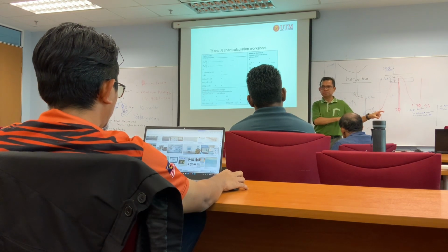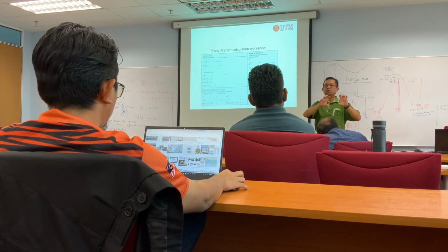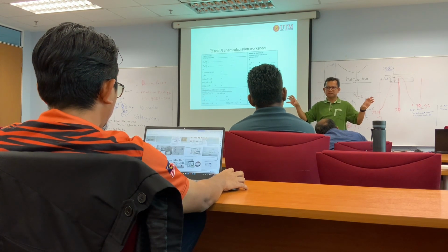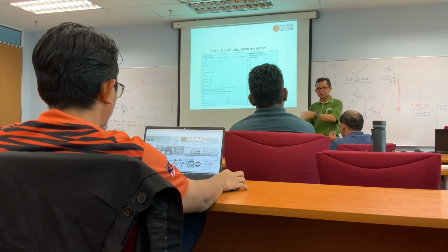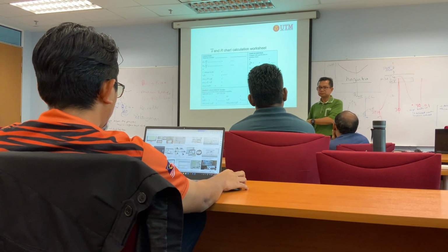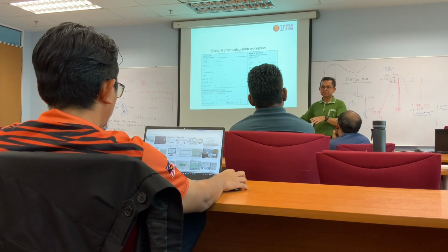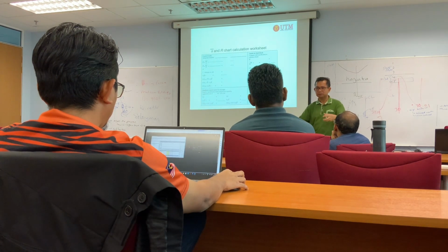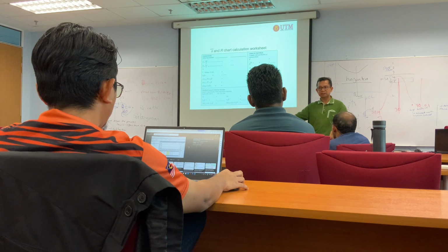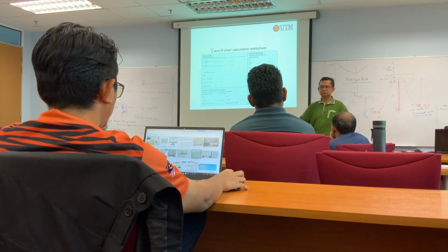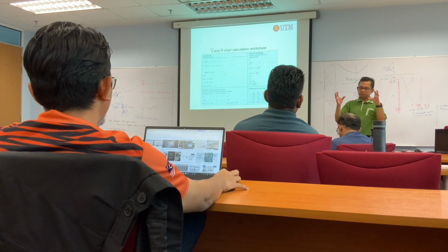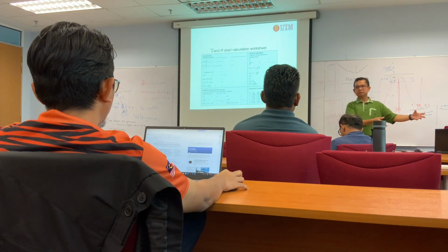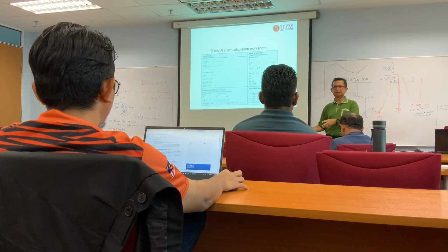Maybe the raw material that you got, the crank, what we call raw cast. Raw cast, you understand what raw cast? Raw cast is the cast product that is raw after going out from the casting process. We pour and then we knock the sand and then we got the raw cast. After we clean and we remove all the edges, and then we bring the raw cast for the machining. So maybe the raw cast quality.